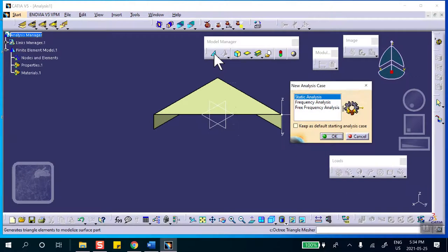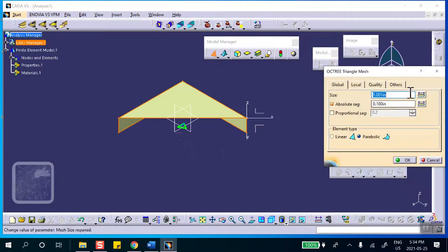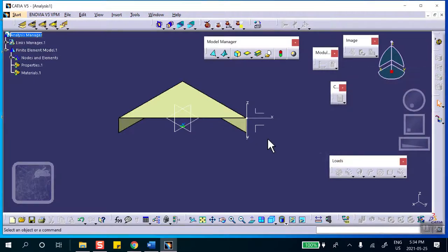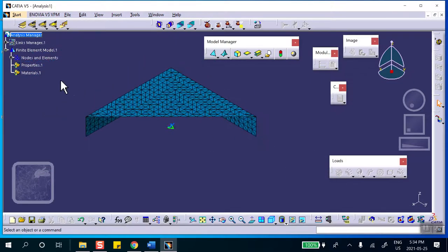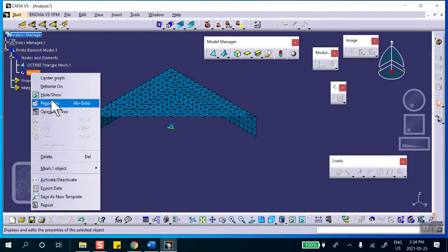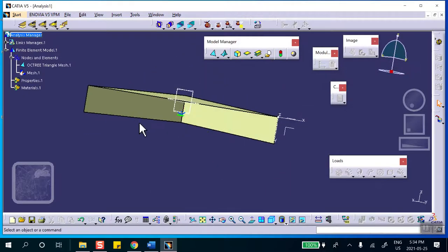We are using a surface mesh shell right there. You click on it. Okay, so that's fine. Let me make it 0.5. How about that? If it's too small, we're going to change it. Okay, good. You want to look at your mesh? Right-click, Mesh Visualization. There we are. Deactivate this. Deactivate it. Okay, the bottom is clamped. This and that are clamped. So clamp.